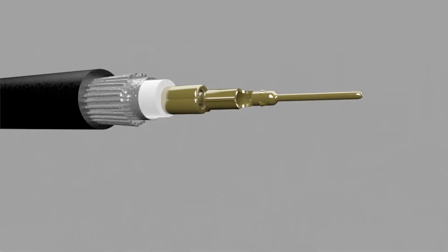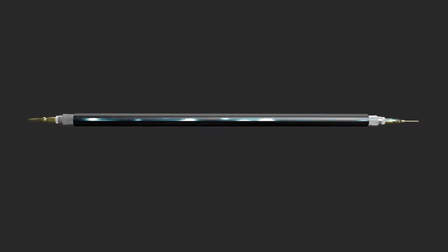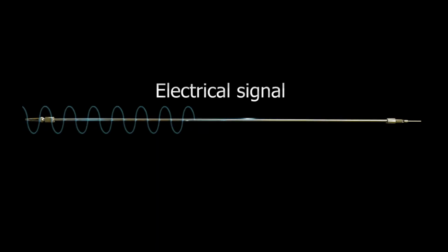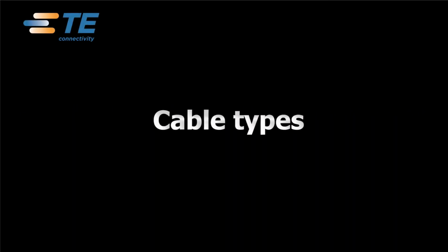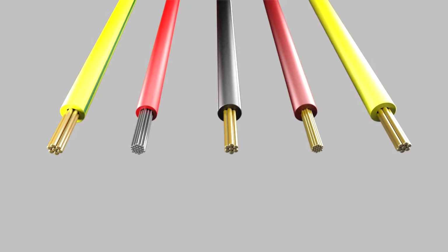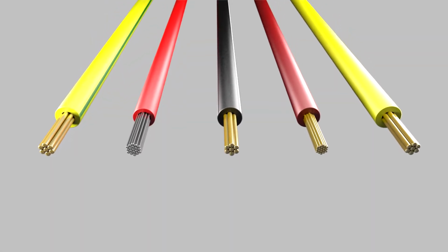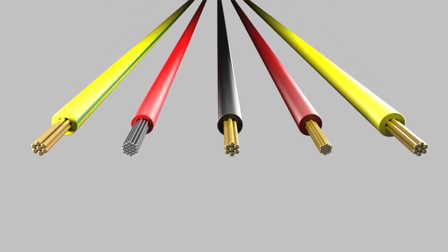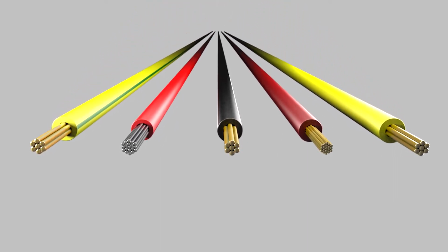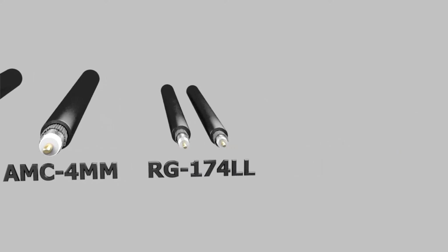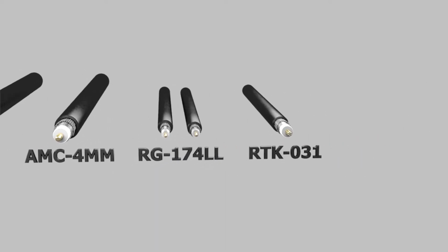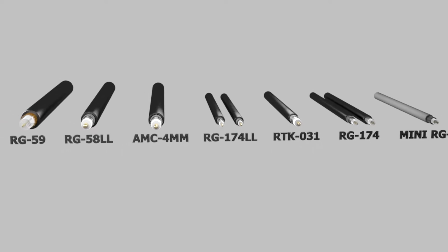The primary function of the coax cable is to carry radio and video signals, measurement and data signals, DC voltage for proper functioning of the car and its various subsystems. Various cable types are used depending upon application and customer needs. Differences between cable types normally can be seen in impedance of the cable, center conductor material, number of conductor strands, center conductor diameter and area, dielectric material and diameter, weight.